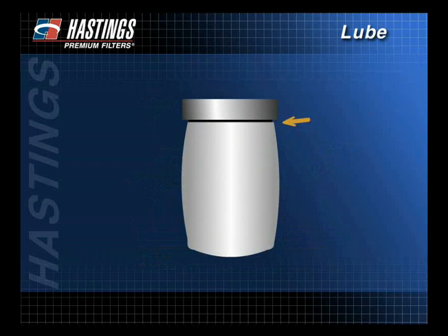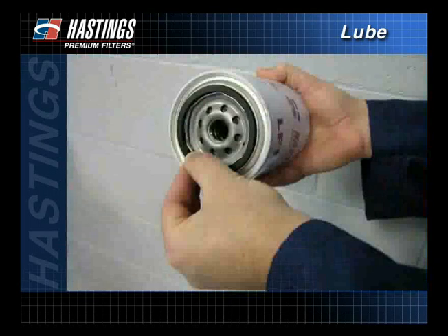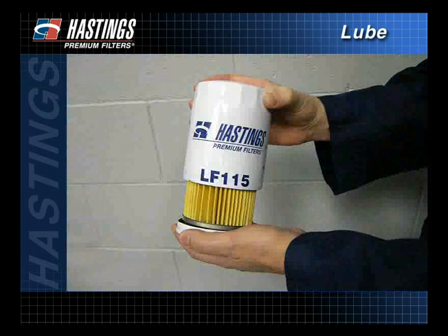Gaskets are displaced from filters due to excessive lubricating system pressure, insufficient gasket compression, or a combination of both. Generally, if the gasket is properly installed, the filter will become deformed before the gasket is displaced. Inspecting the inner element may detect additional problems found in the lube system.